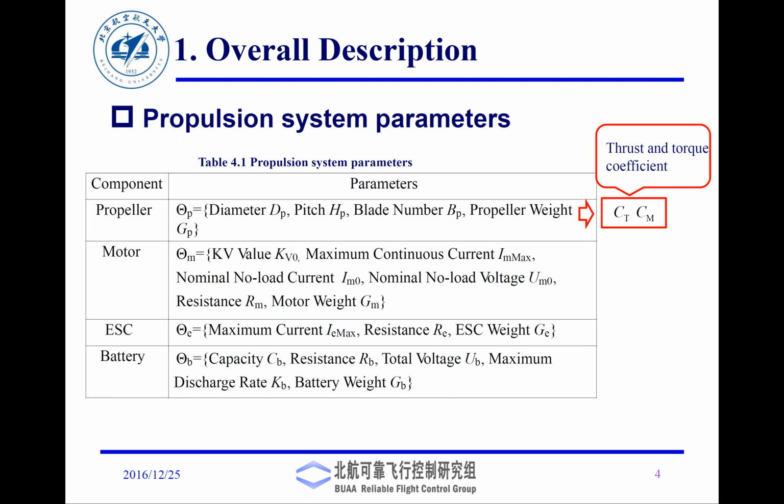But the leading edge is super sharp, because what we want is for the airflow to separate and stick to the outer and inner surface, the top and the bottom surface. You do not want flow to separate. Flow separation is dangerous. Flow separation is bad. That's why the leading edge is super sharp, and the trailing edge is dull. Then you have the blade number, which is nothing but the number of blades. We will also have the prop weight.